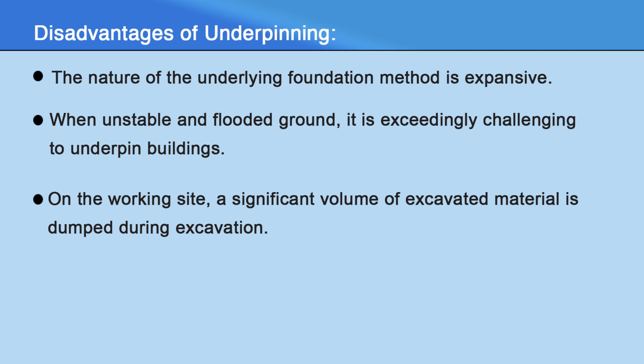Now come to the summary. When the building walls are swelling out or cracks result from unequal settlement of a foundation, shoring is employed to stabilize the structure. It is employed when they demolish a building, neighboring buildings or expand the existing opening in the walls. And underpinning is a technique used to reinforce and restore the foundation of a building.